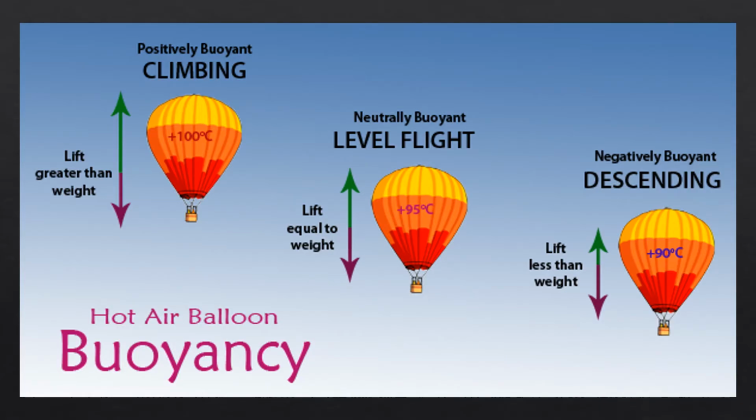To control the balloon's descent, one can either stop firing the burner, which allows the air inside the envelope to cool, thus decreasing the buoyant force, or the parachute valve at the top of the balloon can be opened, releasing some of the hot air, which will also decrease the buoyant force. The goal is to keep the balloon drifting around the desired altitude by turning the burner on and off, allowing the balloon to ascend and descend respectively.